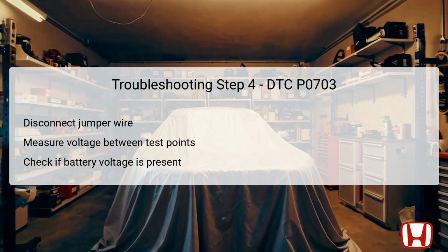During this waiting period, you'll need to prepare to measure the voltage between 2 specific test points: the brake pedal position switch 4P connector number 4, the yellow wire, and the body ground. This is essential for diagnosing any wiring issues present. If you determine that there is battery voltage present at this point, it can be concluded that the IG1_ACG line is intact with no other wiring. Conversely, if voltage is absent, you must navigate back to earlier steps to examine wiring integrity further.